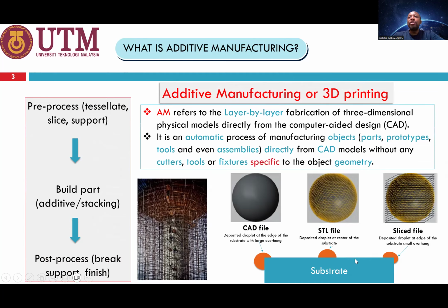But the main issue is if you are depositing the parts at the edges of the substrate, this will result in overhanging. In such a situation, you need various supports at the end of the object to avoid its failure, maybe by falling down or producing components beside the shape you intended to produce.